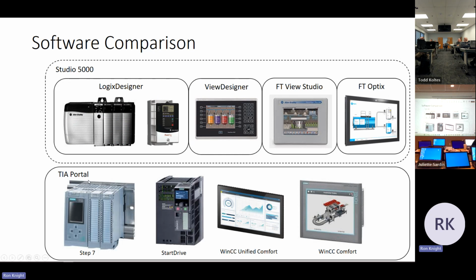So Siemens and TIA Portal. TIA Portal is not a marketing term. It is the software, and then you add components to that software that you need. And they're not standalone software packages. They're all integrated into the TIA Portal. So if you're going to program one of their PLCs, like this 1500, and I'll talk about hardware a little bit later, what that 1500 means, or maybe the smaller 1200, you would add STEP 7 to the TIA Portal. If you're going to commission drives like this G120 drive, you would add Startdrive to TIA Portal.